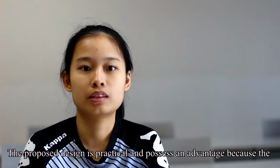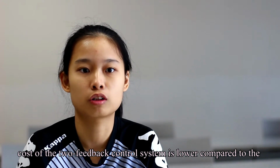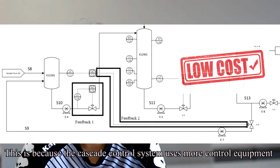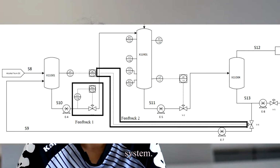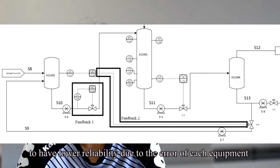The proposed design is practical and possesses an advantage because the cost of the two feedback control system is lower as compared to the cascade control system. This is because the cascade control system uses more control equipment than the two feedback control system, which is an equivalent single loop system. With the use of more control equipment, the cascade control is expected to have lower reliability due to the error of each equipment.